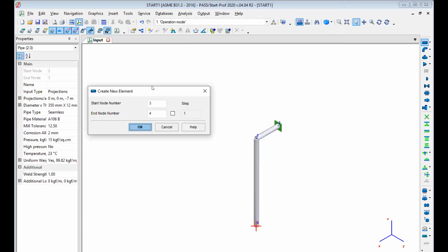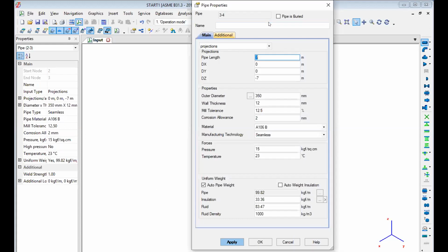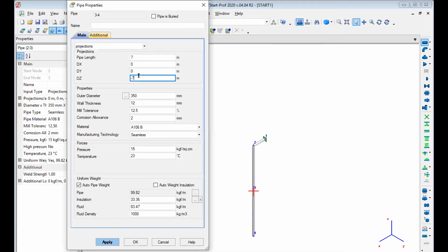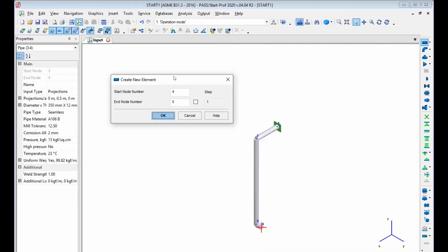Okay. So at this point, I'm going to have my branch off towards my Y-axis. So 3 to 4, yes. And my branch off length, so I take off Z and I go to Y. And I say branch off by 0.5 meters. Apply. All right, I have that.